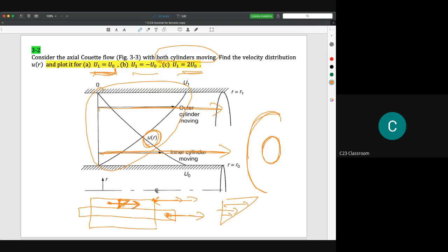So if you want to take UR, you would take the Navier-Stokes equation for R. But the physical motion must be such that, because this is an R, the molecule of fluid must move parallel with the R direction. This motion does not occur, so that's why we cannot take the Navier-Stokes equation for R. Which means basically we pick the axis where the fluid moves, right? Yes. First you need to imagine on what axis the fluid actually moves. Okay, thank you.